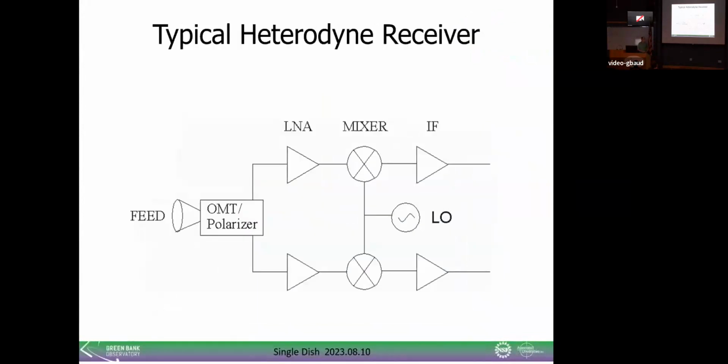So these are all heterodyne receivers, most of them. We have some total power detectors, but all of the block diagrams look the same. There's a feed, an OMT, a polarizer, an LNA, and then after you come out of the dewar, most of these have an IF section with a mixer and an IF amplifier and a bandwidth that sets the bandwidth as part of the receiver. After that, this IF output goes into our common fiber optic links, of which there are 8.